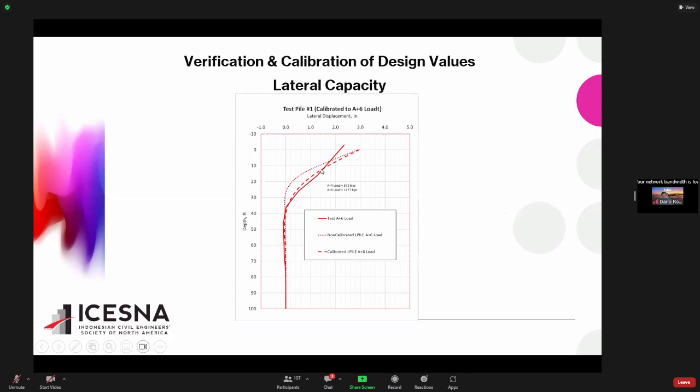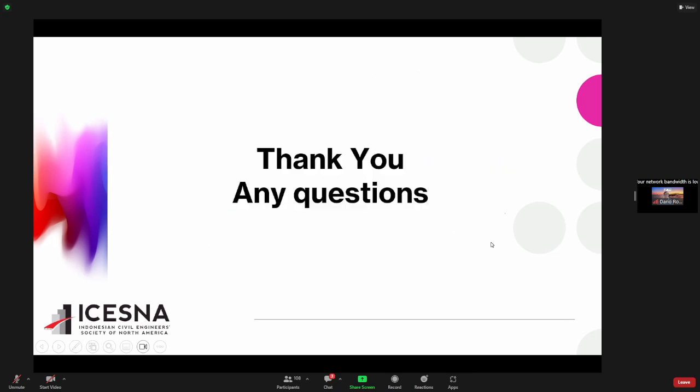As you can see, the shape is a bit different. I don't think we can predict this double curvature. So we end up using this red line for our design. It does not exactly match the test result, but somehow captures the overall profile. So the useful design is this one. This is the pile. I think that's it. I'm sorry, I had to run through it fast.